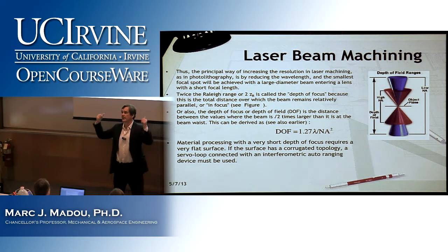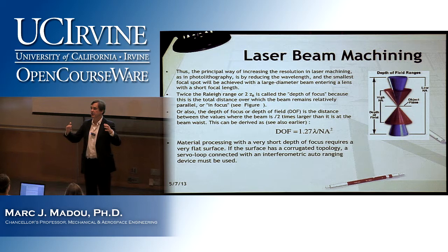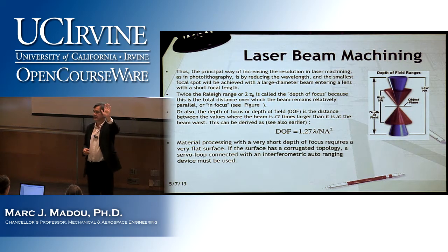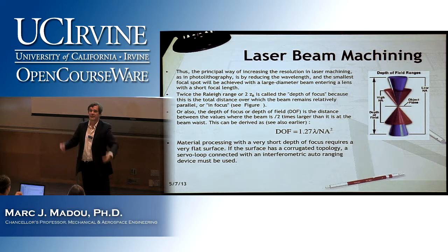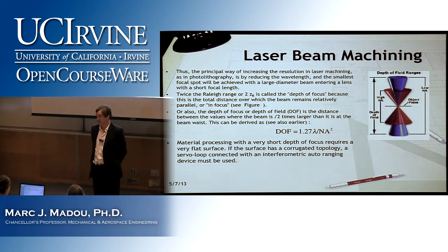So again, without looking at it, what happened there in photolithography? Resolution R. When we make NA bigger, the resolution gets better, right? A smaller number. But unfortunately, the depth of focus, what happens if the resolution gets better? Decreases. And why is that bad?